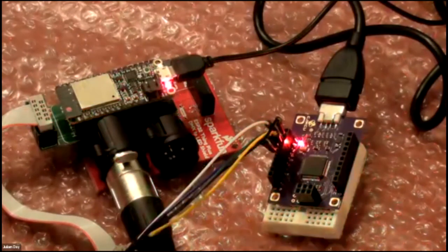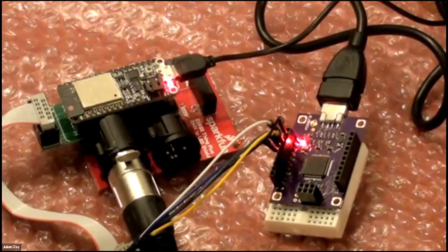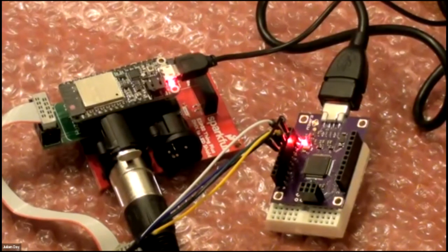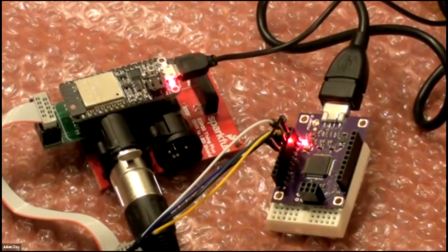Julian, so is SWD a subset of JTAG? Well, not really. I mean, JTAG isn't well defined in terms of the commands that you're issuing to a particular processor to get it to do things. It's really much more about that synchronous serial interface and clocking in instructions. The instructions you clock in and what the data means that goes with those instructions is entirely at the behest of the chip manufacturers. And so Espressif with its ESP32 will be doing completely different things to ARM, and different things to Power.